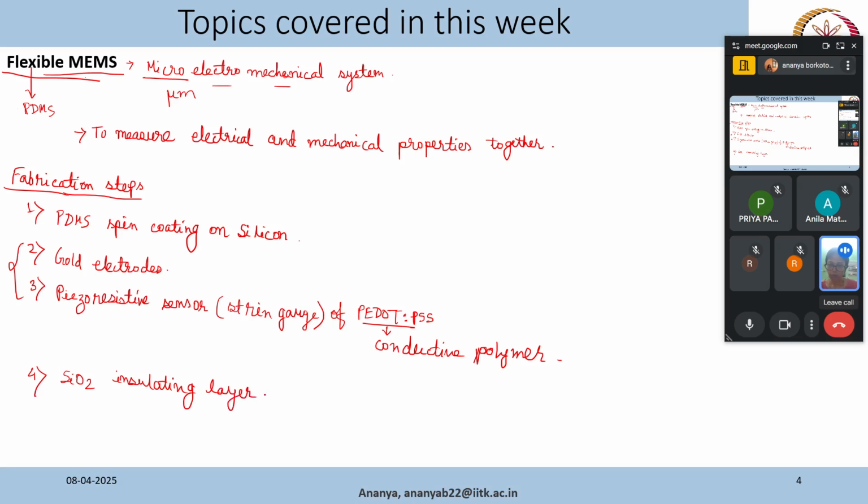And we will use PECVD for that. As I mentioned, we are using a flexible substrate and materials that cannot sustain very high temperature. That is why we will go for PECVD, which requires a relatively low operating temperature, around 200 degrees Celsius.